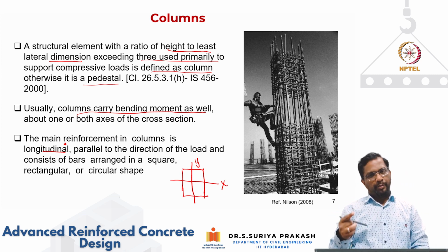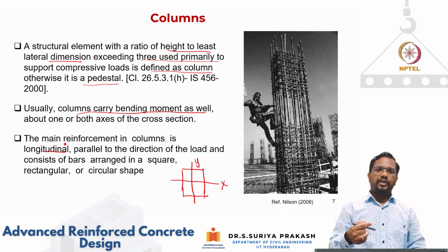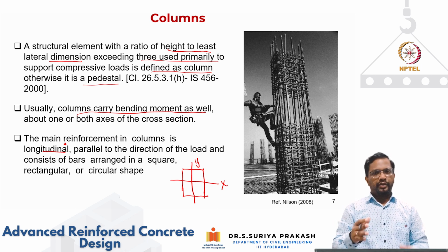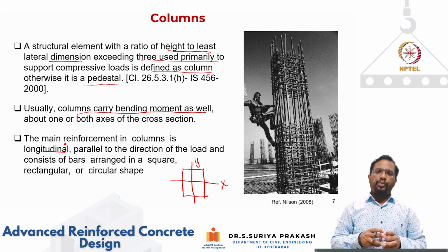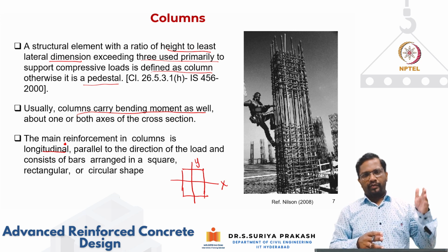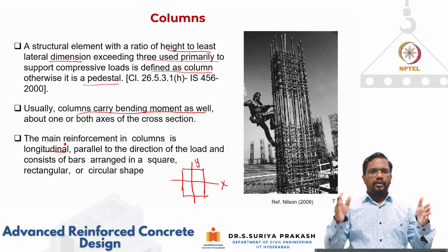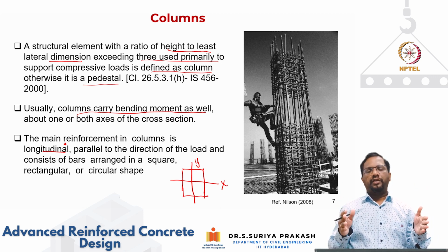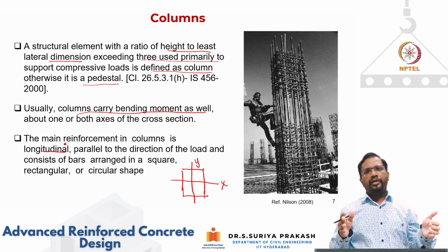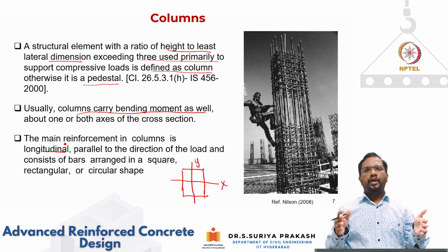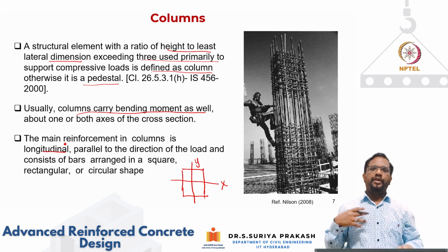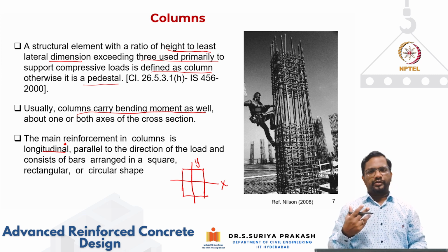However, in bending, we have done the moment curvature analysis. When columns are subjected to pure bending, they have reinforcement on the compression side as well as on the tension side. In fact, usually columns will have symmetrical reinforcement. Because you have the same area of steel on compression and tension, in pure bending such sections will behave like an under reinforced section.